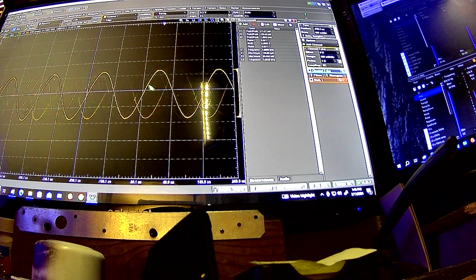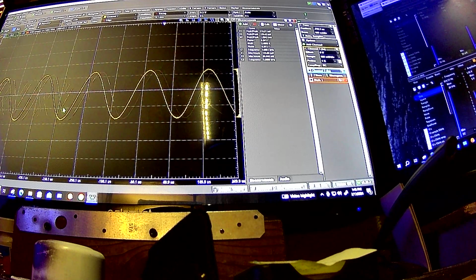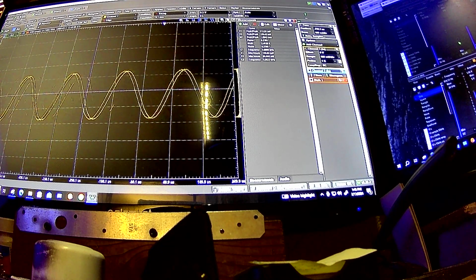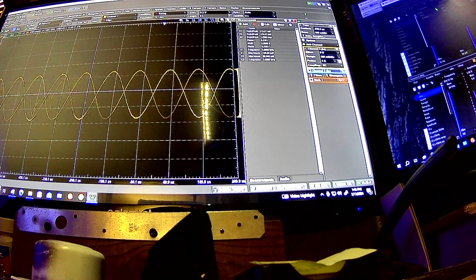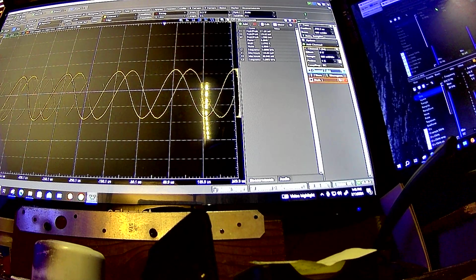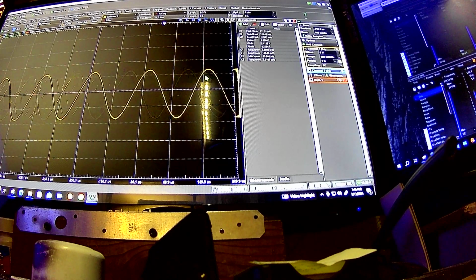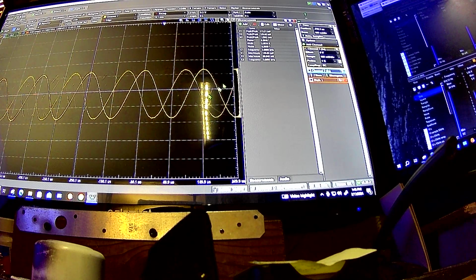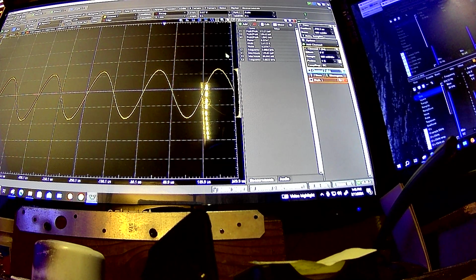And see, this is all kind of buried in hash and stuff. This thing probably does have some kind of filter, because it's got its own op amp in it, so it probably is filtered. But again, our resolution is severely limited by that fact. Let me cut it down to 10 millivolts if I can. Nah, it won't let me go below 50. So at any rate, that's about the minimum signal this can generate. I don't know what its actual resolution is.